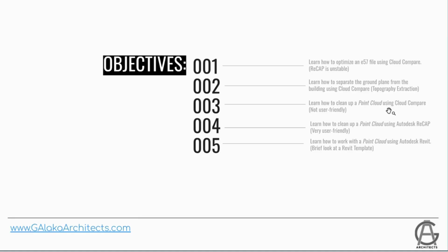I'm going to show you how to clean up a point cloud in CloudCompare, which, at least for me, is not a very user-friendly interface, but it works. The one that does have a very nice interface is Recap. It has a very nice way of cleaning up the point cloud, even though it's a little bit manual. However, CloudCompare has a lot more buttons and things that you can do to manipulate a point cloud, while Recap just looks prettier. It has a lot fewer things you can do, but it's a little bit more user friendly.